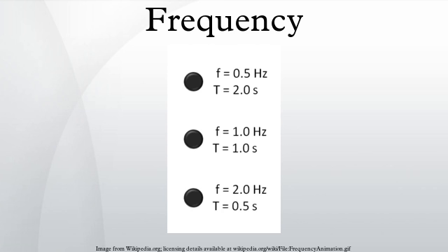The strobe light is pointed at the rotating object and the frequency adjusted up and down. When the frequency of the strobe equals the frequency of the rotating or vibrating object, the object completes one cycle of oscillation and returns to its original position between the flashes of light, so when illuminated by the strobe the object appears stationary. Then the frequency can be read from the calibrated readout on the stroboscope.